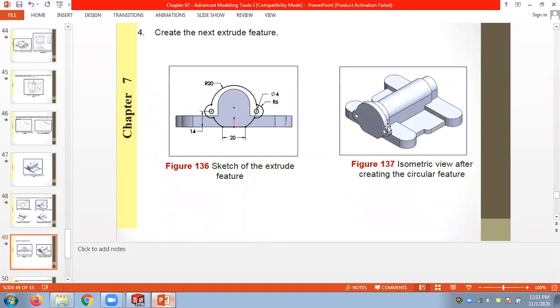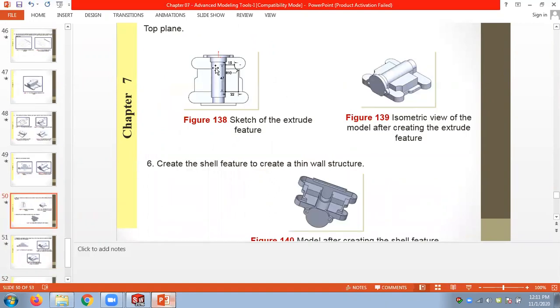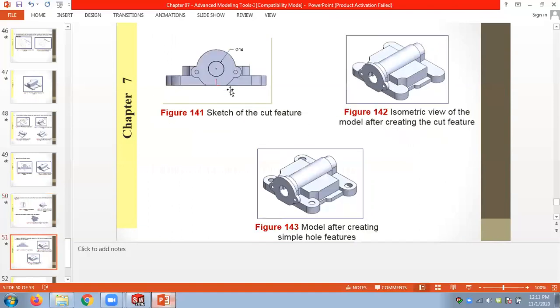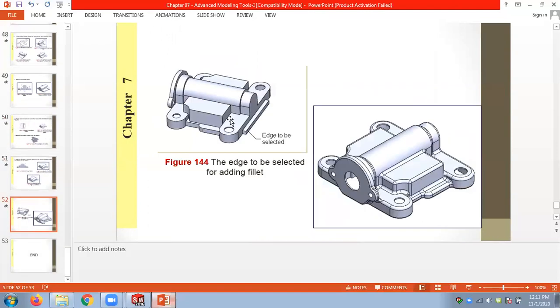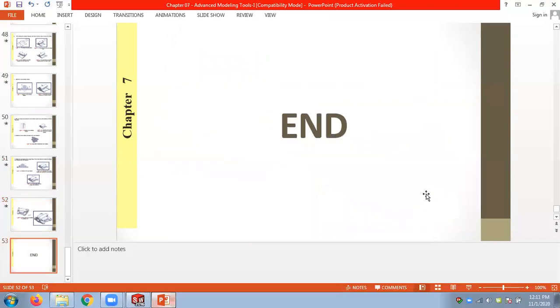We have drawn this bracket shape separately, and we have drawn these two boxes separately and applied the shell feature. We didn't discuss this at the moment. Shell feature removes the material inside, and then we can have cuts. So cuts can be done at the end. When you have a 3D solid object, you can easily cut them. So no problem. And apply the fillets here. Later we can apply the finishing and fillets there.